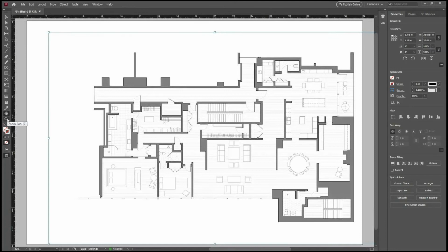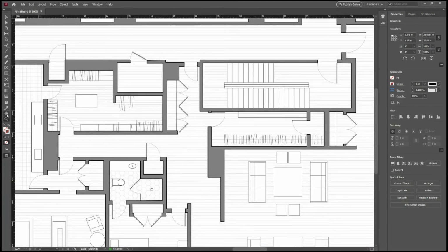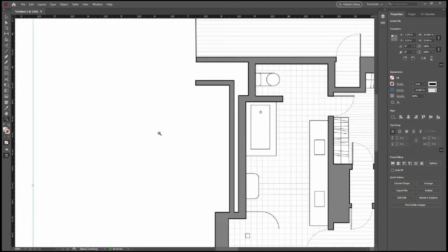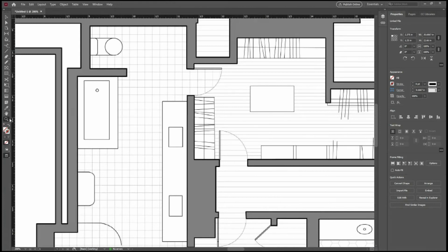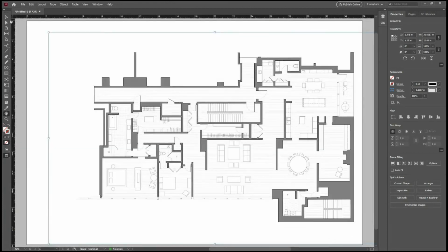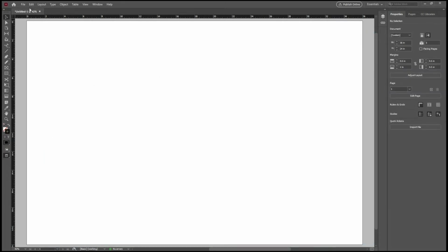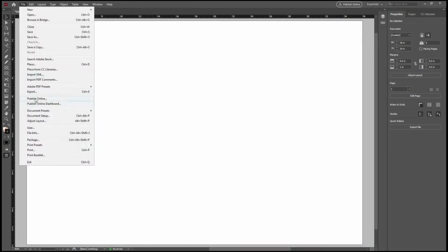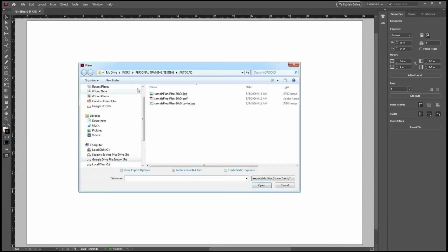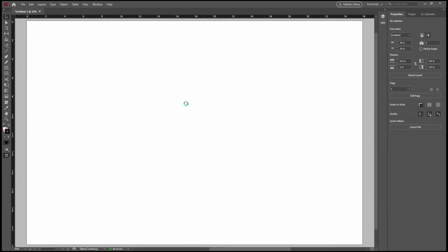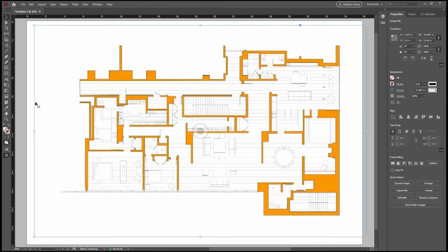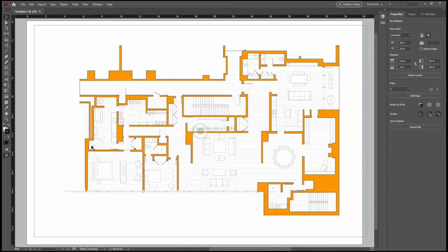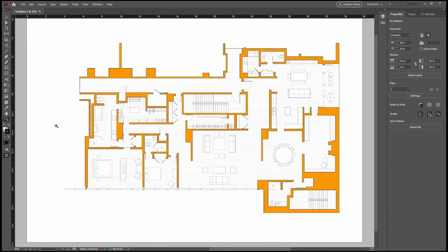So these are coming through as a JPEG file. And you can kind of see close what the quality looks like. Double click on the hand to zoom out full. Now, I'm going to delete that and try the other one. File, Place, color. Double click. Again, place it on the screen somewhere upper left. It's nice and big. Escape, escape.